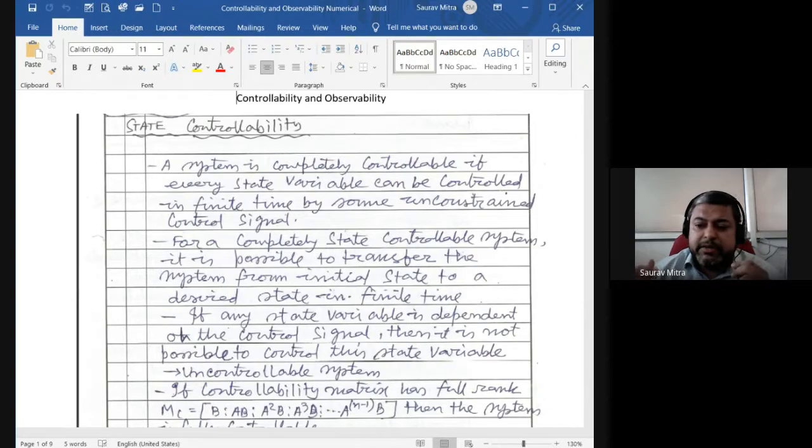So I gave you the differential equation. From there you found the transfer function. From there you could find the state variable model, and you could find the ABCD matrix, provided the output is given. If the output is not given, automatically you have to take y(t) = q1(t). Once you had found the state variable model from companion form, the last thing was, from this ABCD matrix, to find the transfer function. Once you find the transfer function, you do the cross multiplication, take the inverse Laplace transform, and you can find the system equation. So this is a chain.